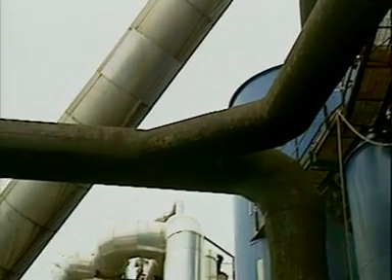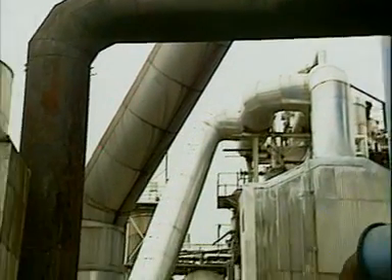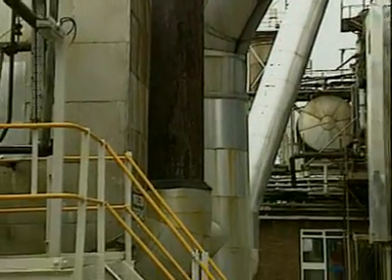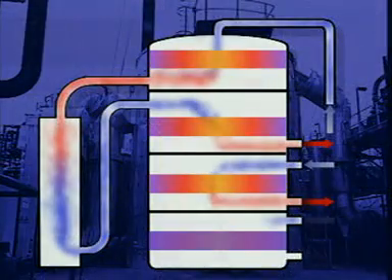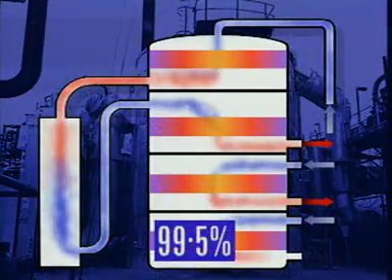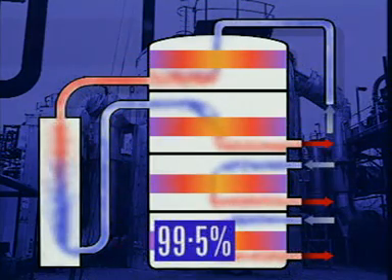The gas from the top of the tower still contains some sulphur dioxide and oxygen and is fed back into the final bed of the converter, after which 99.5% of the original sulphur dioxide has changed to sulphur trioxide.